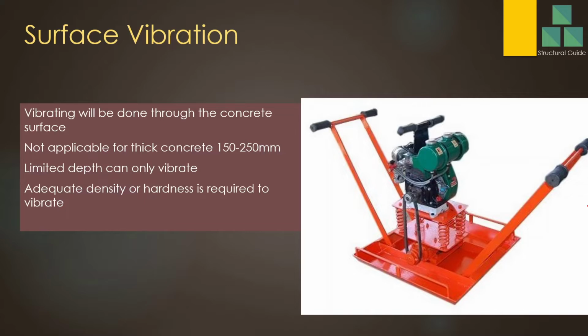Adequate density and hardness is required, because you can't move this machine over the concrete surface if it is not adequately hardened. For very highly workable concrete, we may not be able to apply this method.